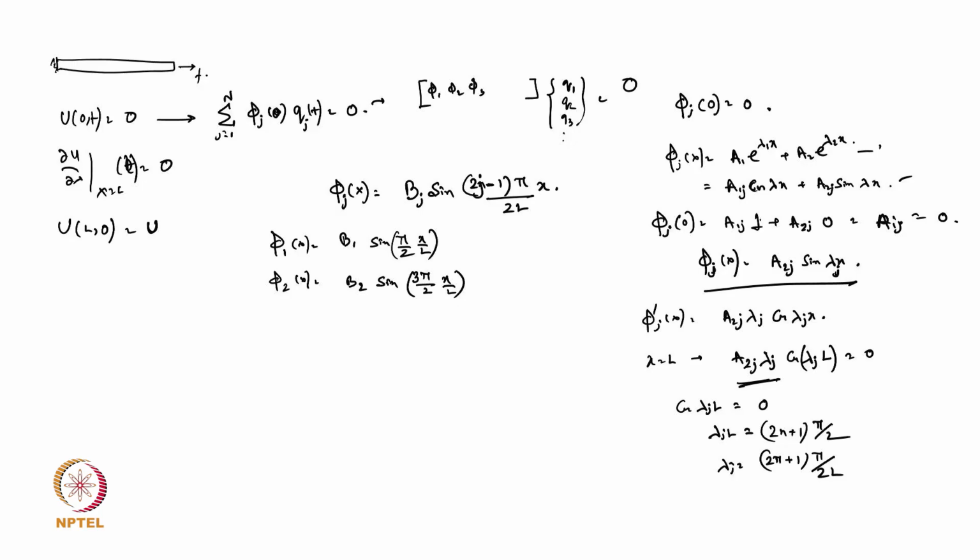Therefore, you should understand that when solving a cantilever beam, your shape function, and when solving a simply supported beam or a bar like this, they all will be different. Whereas in finite element, they all are the same. So your life in finite element is much easier. You just have an element, you just put it, done. You are not thinking anything behind that, about what should be the better way of approximating it. You are just using it.